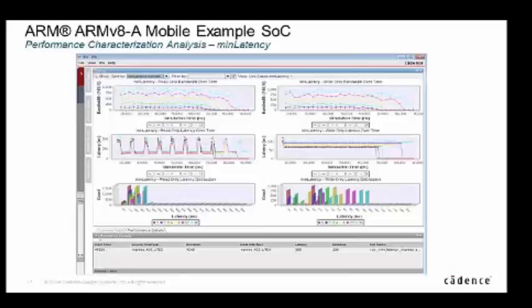Not only cope with it, but debug if something goes wrong, how do you debug it, right? That's the whole essence of trying to start simple and add, if you like, realism into the process, because the realism makes it very difficult. So what we do is for each master, you would say, I want this much read bandwidth, this much write bandwidth, this is the address pattern, maybe even down to the degree of these are the AMBA transactions I want it to use, because you know your IP has that kind of behavior.